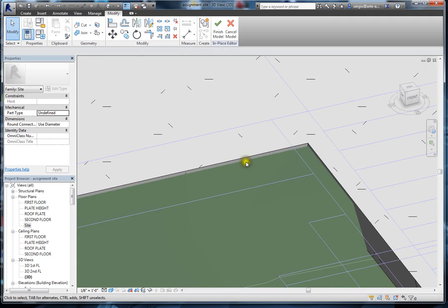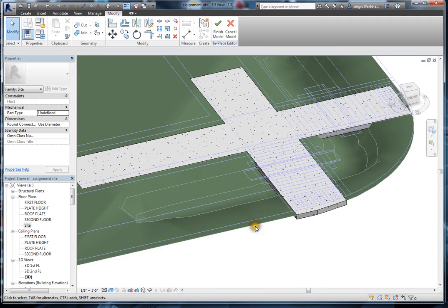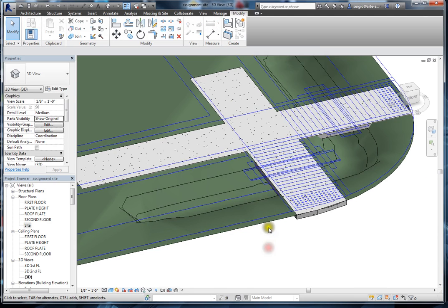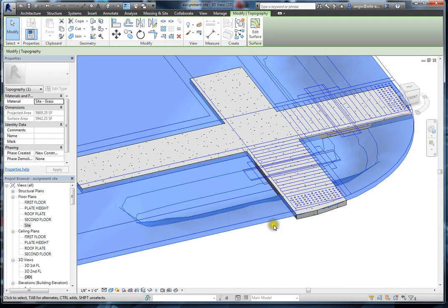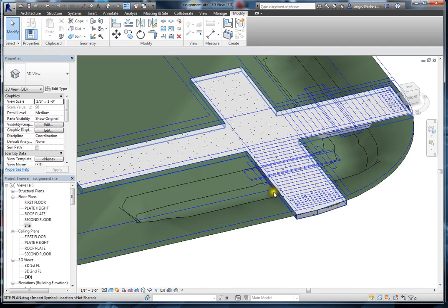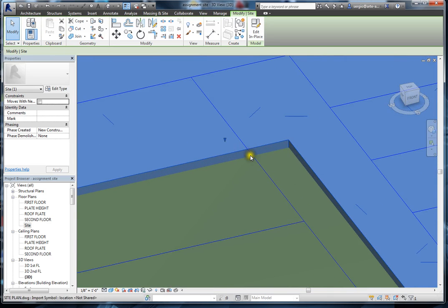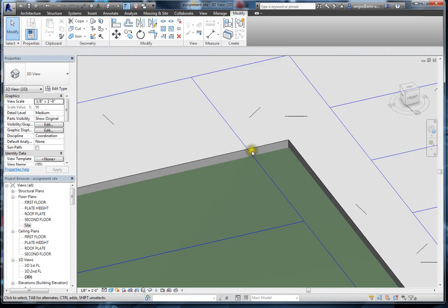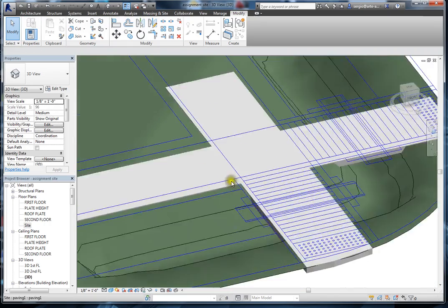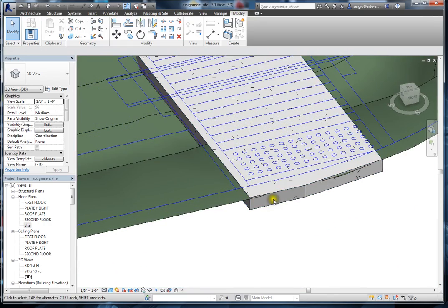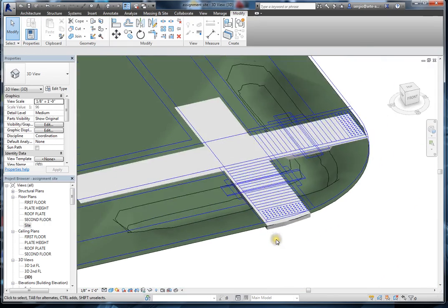So remember that when we created the Toposurface, let me finish my model, there we go. We created this one at minus 6 inches below our working plane. And then we created our sidewalk at minus 5.5 inches. So that's why we see a 1/2 inch of the sidewalk sticking above the grass. That's okay, that's what we want. And then I gave it a thickness for the sidewalk.